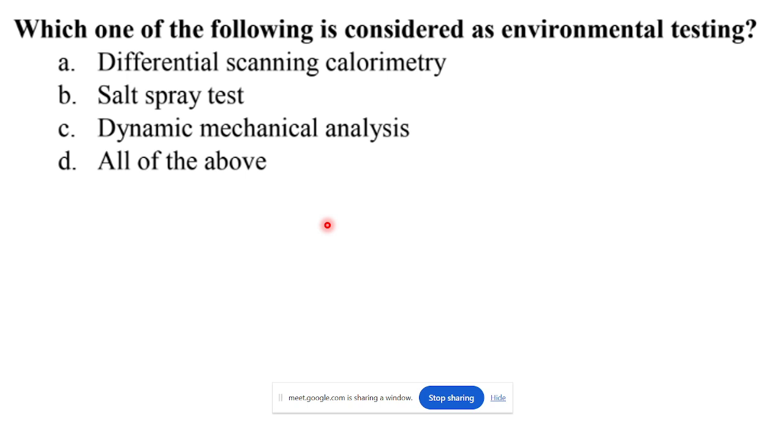From the DMA, you cannot say the entanglement. I mean, actually, what is cross-link density? Cross-link density is the number of cross-linking sites per unit volume. So, say you are using sulfur to cross-link your rubbery material. If you use a higher phr of sulfur, the cross-link density will ultimately be higher. Now, the higher the cross-link density, the more difficult the segmental mobility. Now, if cross-link density is higher, your elastic component is increasing.